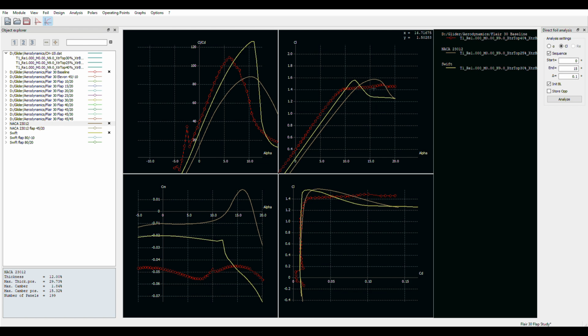And with this airfoil, that comes automatically built into the airfoil in this drop off in the lift curve slope and the early separation on the trailing edge of the wing. And you get both a physical and an auditory warning that you're about to stall. Now, my CM curve, pretty much like the Swift, and mine's only minus 0.01. I have the lowest pitching moment curve out of these three airfoils at 0. So that means I need either less washout in the wing, less reflex in the airfoil, or less up elevon to achieve pitch trim. And that holds pretty good until I get out here to about 10 degrees, and then it starts to go up kind of quickly.